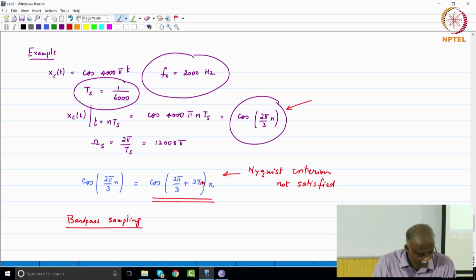Samples will be produced all over the spectrum. You take that portion of the spectrum which is closest to what you consider as baseband. So actually bandpass sampling, or in our context just the sampling process, can also be leveraged as a method of frequency down conversion.